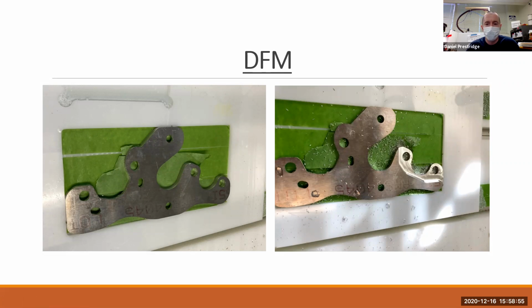And if you're making this for yourself, you have to think about, how am I going to cut this? How am I going to set it up? How am I going to re-indicate on this part to cut the other side? Because if you cut one side and you flip it over, how do you ensure that you're going to cut in the right spot?